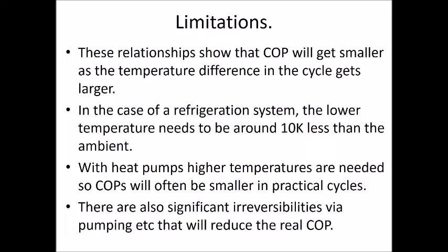We'll also get irreversibilities if we're pumping very hard against big pressures. So you get things like flow and separation losses as the refrigerant screams across the throttle valve, etc. So these are all really interesting things that we need to consider if we're going to model these systems and how they work. But the driving factors all come from what you've seen in these examples here.